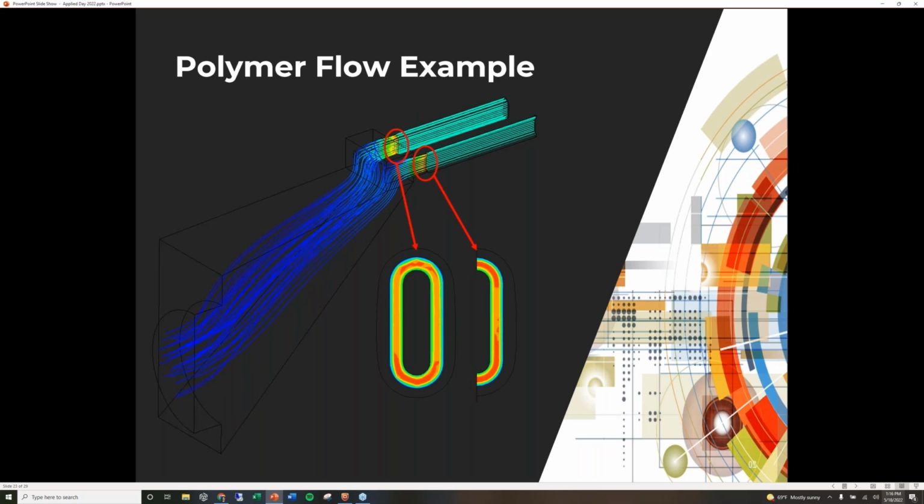If we look at a close-up of this, this is a velocity contour close-up at the die lip. We can see that our die is not very balanced. We have some large velocity gradients in the exit section, so this could lead to some quality control issues. And the black line that's surrounding our velocity contour is actually the outer edge of our extrudate profile. So that's, again, really outlining the polymer swell as it exits the die there.